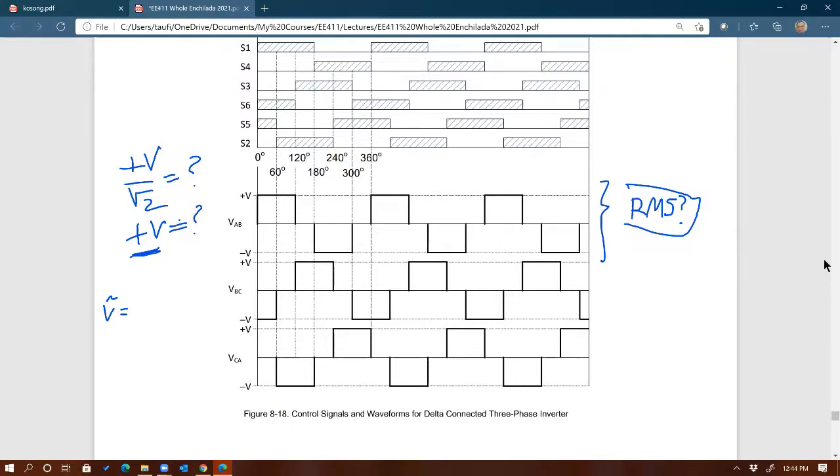I'm glad that you remember that this is going to be a function of duty cycle, meaning you're going to square it. That means the RMS of this is the same as the RMS of this waveform right here, because you're going to square it anyways. So therefore, the RMS of this waveform is the same as the RMS from here to here. You agree? Yeah, I don't need to include the negative.